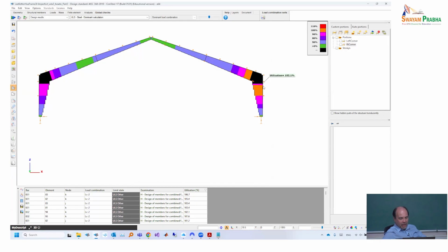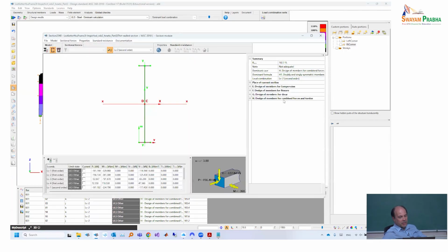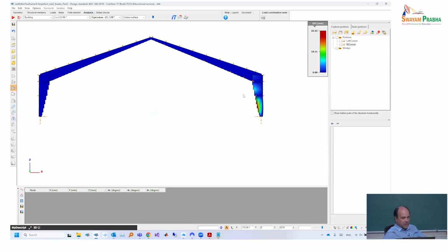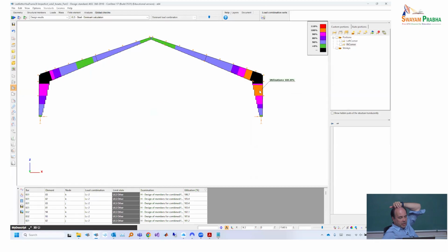But if we go again to this cross-section, what we wanted, then we will see that now, nicely, without saying anything, not the very first mode was used for the column, but something else. Let's see what was the 3.88. 3.88 is definitely the second buckling mode, which belongs to the column. So the first is still for the rafter, without me selecting this mode and forcing the calculation to be performed for this mode, Consteel was automatically using this mode for the column.